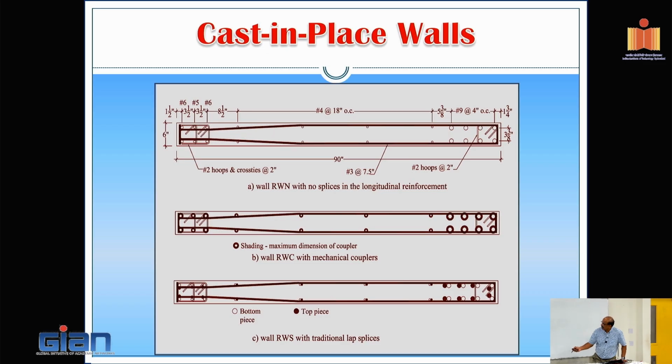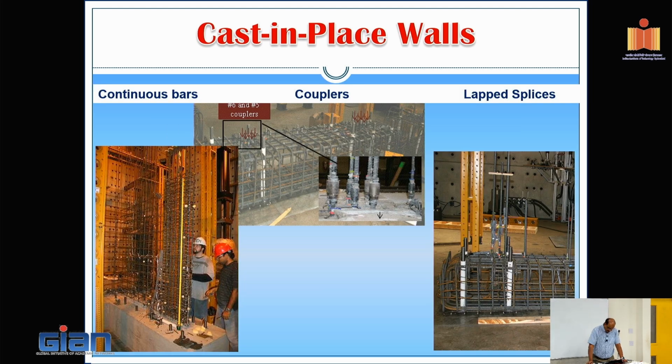When you introduce couplers, you can see that you need to have sufficient room to accommodate couplers also. So putting in couplers is not just a straightforward thing. You can't just replace and put one in there. It causes some challenges as well. So you can see in this one where the couplers were located, how the walls were designed and built. Clearly the couplers were located outside.